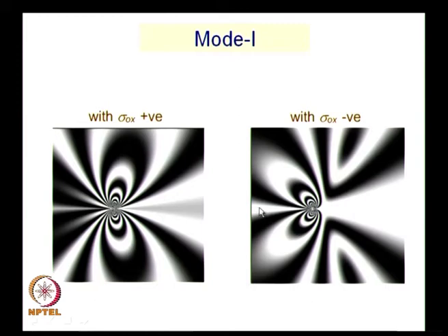Suppose in this specimen also the crack advances and comes closer to the boundary, imagine that this is the boundary of the specimen, then again it is experimentally recorded that the fringes have forward tilted loops and a frontal loop. So, people have seen that when the crack tip is closer to a boundary and it is long enough, you invariably have frontal loops.